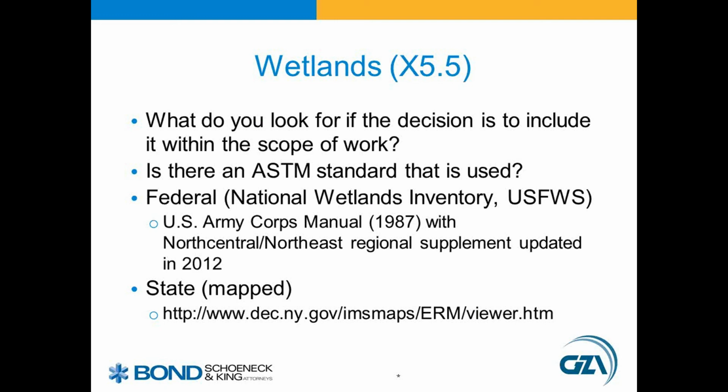Picking up on that, the 100-foot buffer only applies to a state wetland, and state wetlands are, as Ben said, mapped. They're large, 12.4 acres unless they're unusual wetlands that the DEC has decided to protect, but generally it's 12.4 acres. And again, you do have that additional 100-foot buffer that protects them, so there is a need to put that into the calculation in terms of developing in that area. What people don't realize is that there is no federal map.